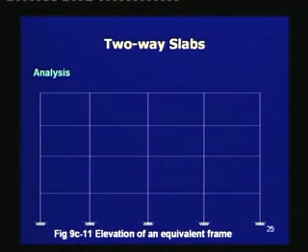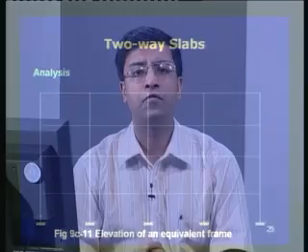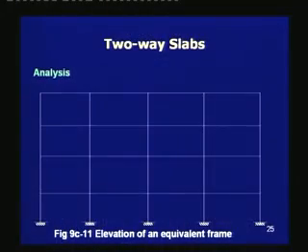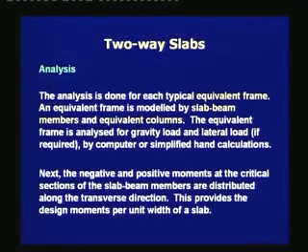Now once we have defined the equivalent frame in the plan, we see also the equivalent frame in the elevation. The elevation depends on the number of stories, and it also depends on whether there are any breaks in the columns or not. Now given this equivalent frame, we start the analysis. The analysis is done for each typical equivalent frame.